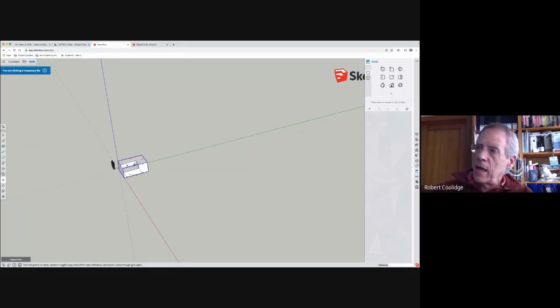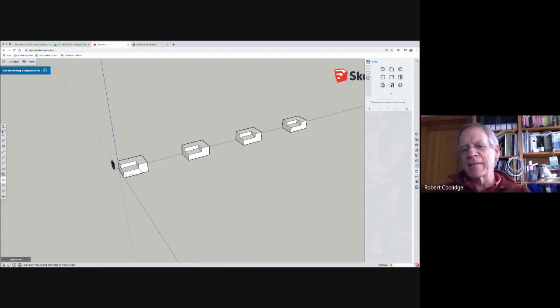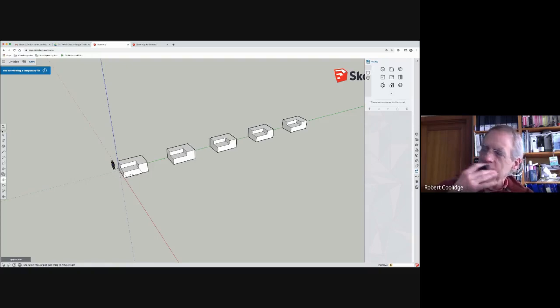In a similar way, if you take the Move tool, hit the Option key, drag it out some distance, click, and then type 3 divide, it equally spaces them from the first one to the last one. You can play with this retroactive method of doing numerical stuff. You can say, I don't like that, how about 4? I can type 4 divide, and I can still mess with it, or 5 divide, and see how that looks.